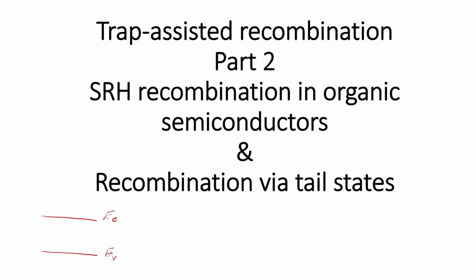However, if we have so-called amorphous material, where the conditions were not favorable for the formation of a very periodic structure and atoms are kind of placed all over the place, and we don't have the long-range periodicity of the crystalline lattice, or for instance organic semiconductors, which, since they are obtained from spin coating and from polymers, cannot obtain this long-range periodicity, then we have disorder in the structure as an intrinsic feature, and energetic disorder, which results in some Gaussian or exponential distribution of density of states.